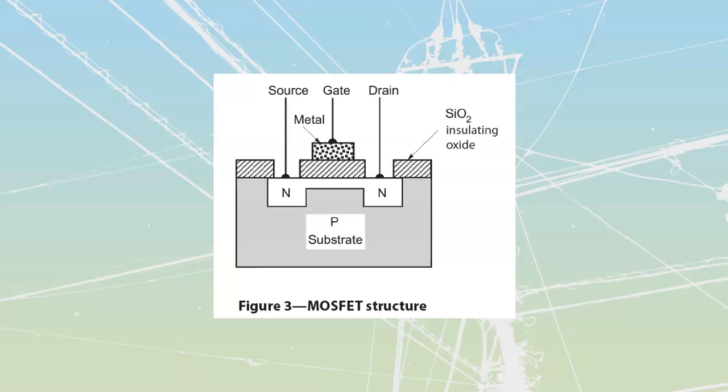And the MOSFET is going to have silicon dioxide, SiO2, that is going to insulate my gate and my semiconductor channel. So it is going to be an additional layer of insulation in between my gate and then my source and my drain over here, which means that I'm going to have even less leakage current that I'm going to be able to pass through this thing, which once again means I'm going to have a better overall device when it comes to my total amount of losses. We want to cut down the total amount of losses because that's how we get efficiency out of our electronics.